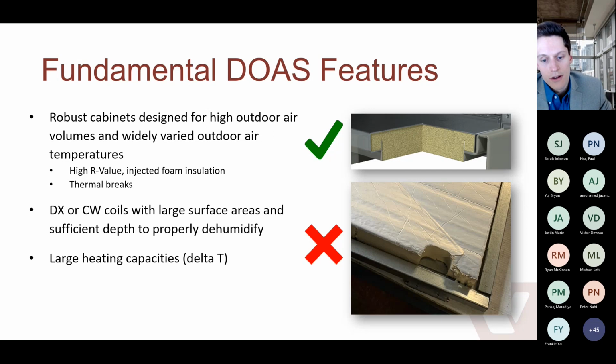If you've got a 3-to-1 turn down furnace, let's say you've got a 60-degree delta T, well, that means your minimum turn down is 20 degrees. And there's a lot of times during the year where you might only need, let's say, a few degrees of heat, right? In the shoulder seasons, you don't need 20 degrees. You're going to be turning your furnace on and off, and that leads to a lot of temperature swings in the space. So you're going to want 10-to-1, 12, 16-to-1 turn down on your furnace, for example, or a fully modulating electric heater, right? Electric heat or air source heat pump, whatever it is, you want to be able to fully modulate your heat, especially.